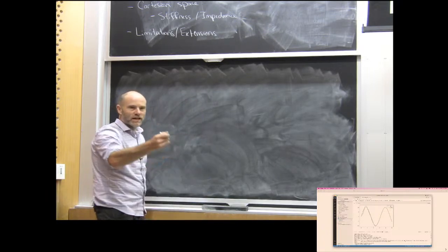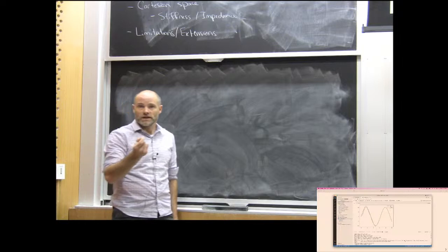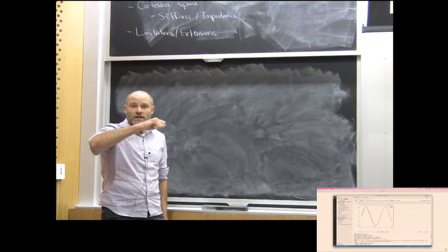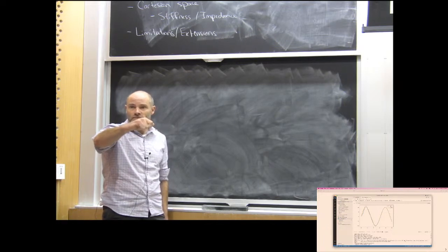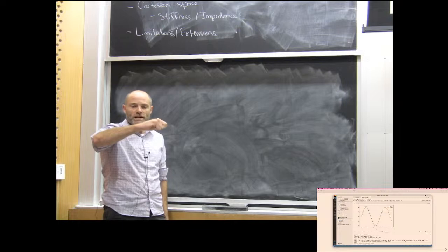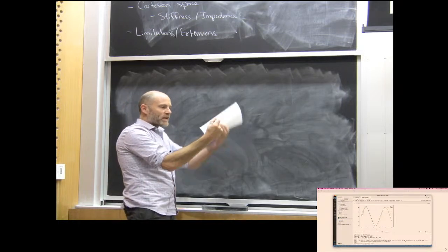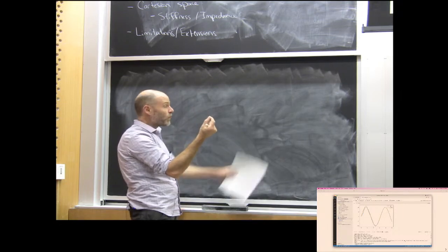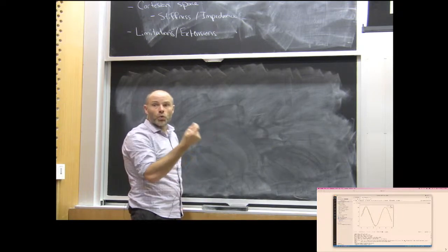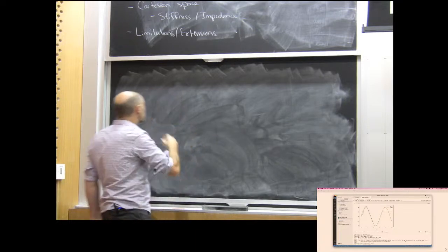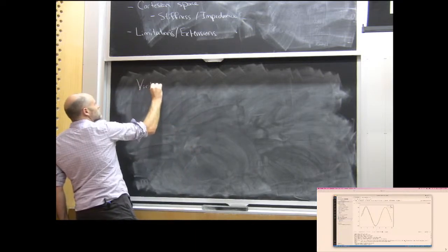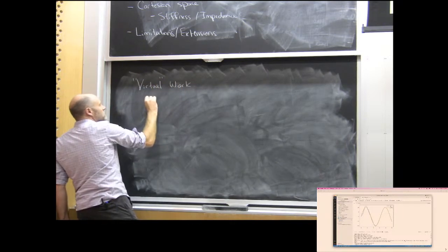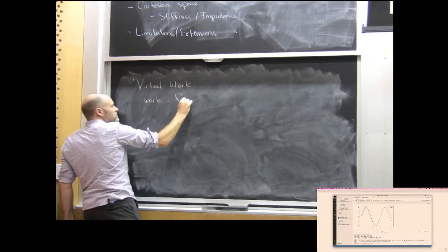It's really simple. Okay, it's just a power argument. If you think about the work actually done at the end effector, this is the way we think about it. So if I have a robot in some configuration, I want to think about the incremental work done at this point on the end effector. Work is force times distance, right? This is an argument of virtual work, it's called. Work is force times distance.